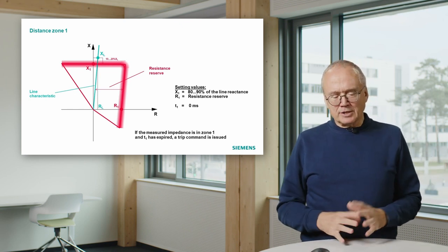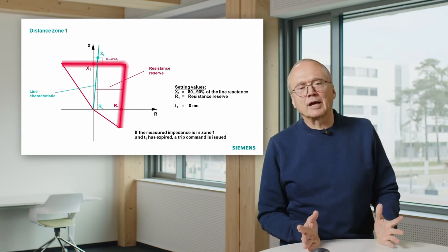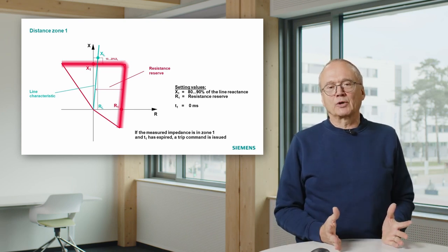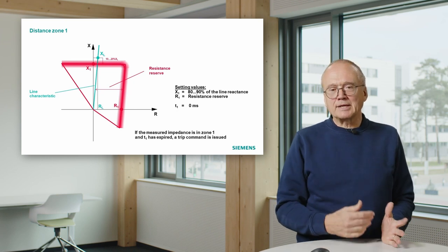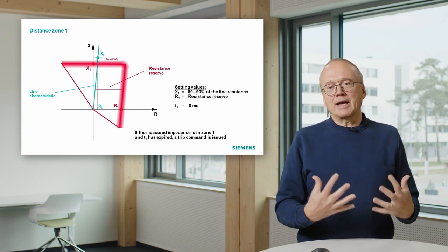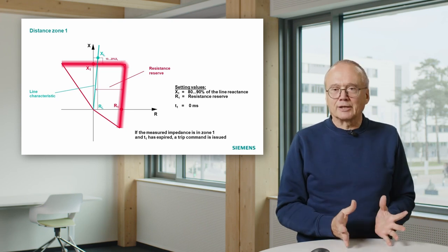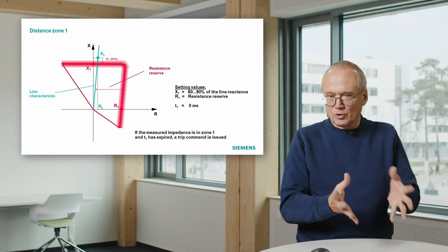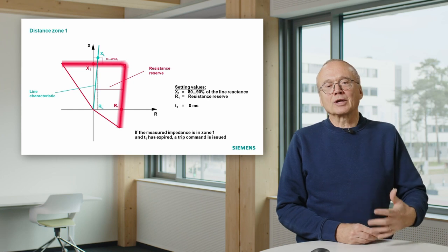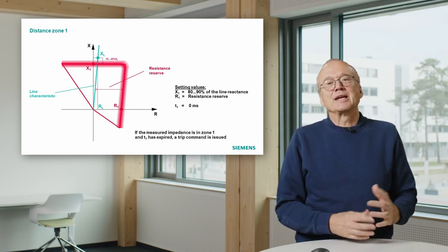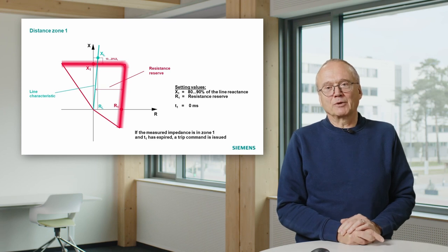But the situation you often have is you have many relays with circular characteristic in operation. You want to replace relays. And if you are happy with the behavior of your characteristic, you have calculated already all the settings for this circular characteristic, you don't like to have suddenly relays with quadrilateral characteristics, even if they have some advantages.